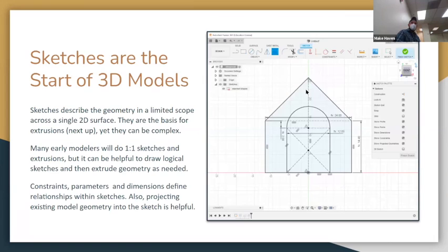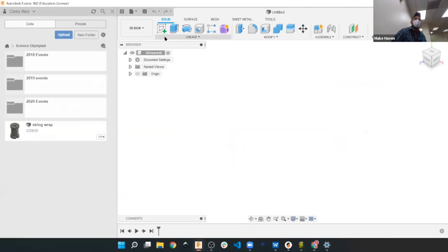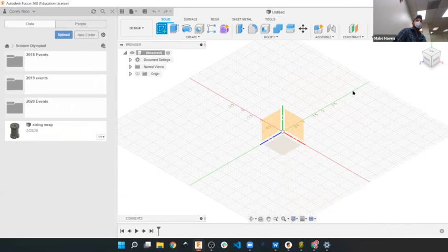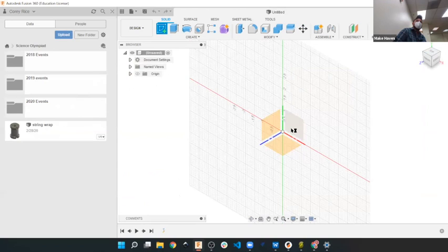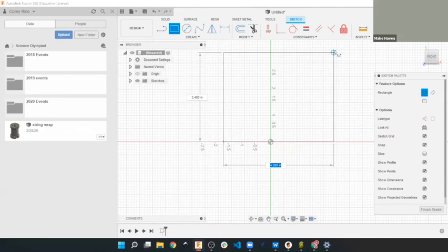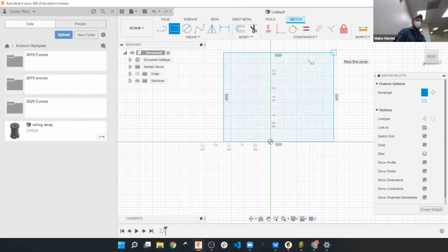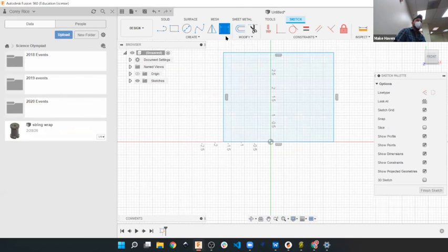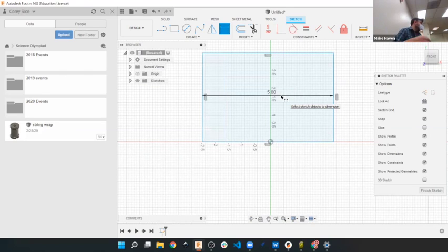Where to set the scale? Ooh, when you're typing in, that's a good question. And I do have Fusion 360 up. If I wanted to make a sketch, I would choose, like, I'm going to do a front view. And then I can set up a rectangle like this, where I just sort of go like that. And in drawing the rectangle, it's asking me what size do I want it to be. So I can either sort of drop it without anything defined, and then I can use a dimension tool, or I could define it in that instant when I was drawing it. So I could say that I want this to be exactly 5 inches wide and set those that way. But a sketch like this is how you'd want to start off most things.